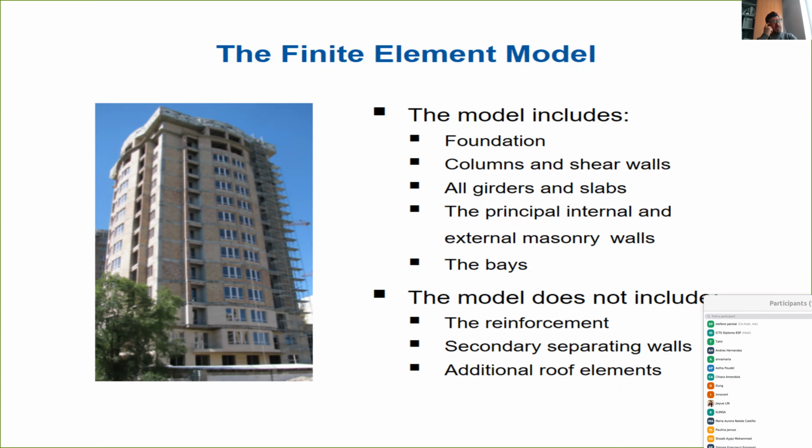But as I said yesterday, for modeling a structure correctly, you also need good starting parameters. And at least these measurements allow you to fix good parameters at the beginning of a simulation, when the shaking is small. How this will evolve and how the behavior of the building will change will depend on these starting parameters and how they degrade with time. So even if they cannot fully represent the behavior of a structure, they are still significant to fix correctly some of the parameters necessary for the simulation.